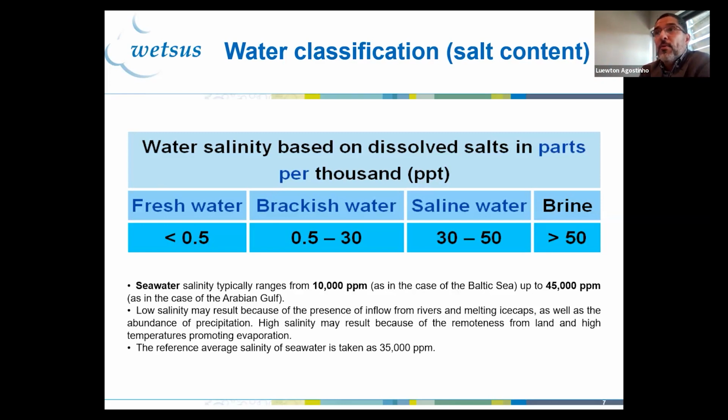So at the end, removing the salt becomes quite a tricky problem as well. We have in the Netherlands, for example, here in the region of Friesland, groundwater that is not salty, but it's really rich in iron and methane. Aeration solves your iron problem, and also removes the methane. That's okay. But salt is dissolved, a non-precipitatable type of earthy metal oxidation, so it has to be removed via a thermal process or a membrane process. It makes the use of brackish water quite complicated in many different locations.